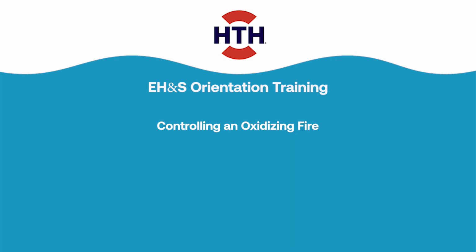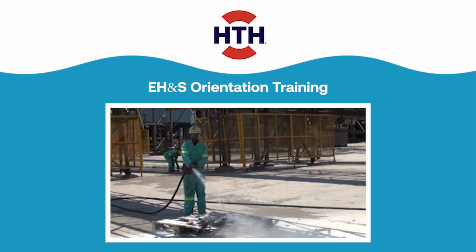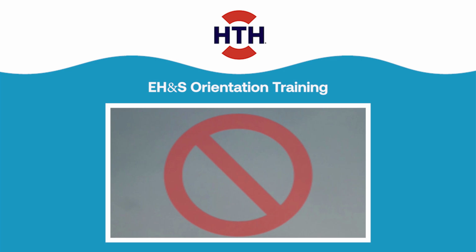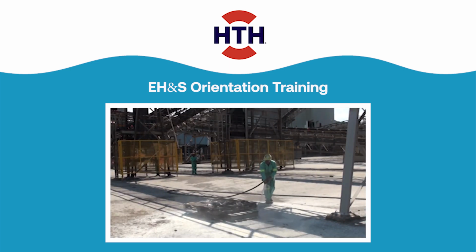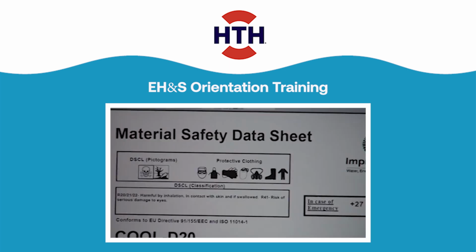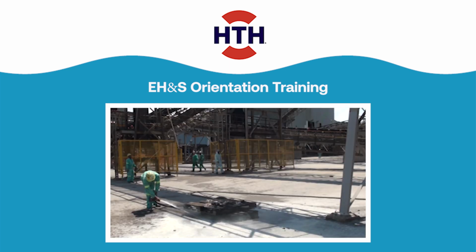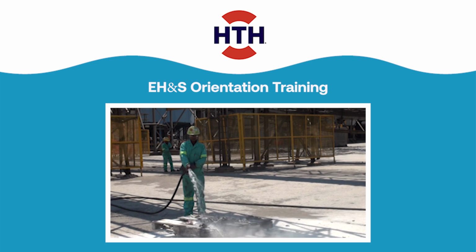Controlling an oxidizer fire. Water is the most important element in controlling an oxidizer incident or fire. Do not use dry chemical extinguishing agent on oxidizer fires. Water in sufficient quantities will greatly reduce the reactivity of most oxidizers. Refer to the MSDS, Material Safety Data Sheet, to determine the characteristics of the specific oxidizers that you are handling. Adding water normally slows the decomposition, reduces liberation of hazardous gas, and eliminates self-sustained decomposition.